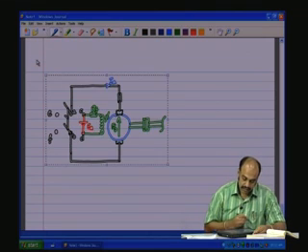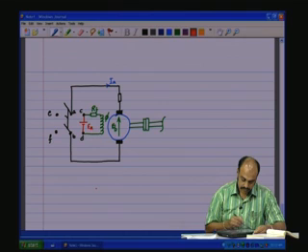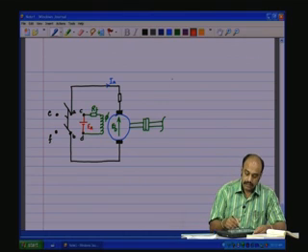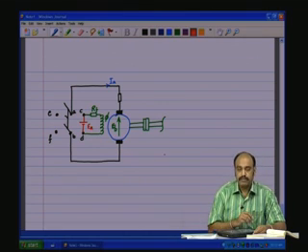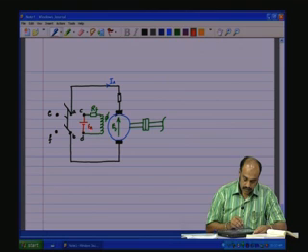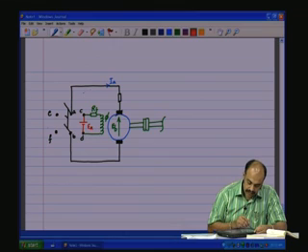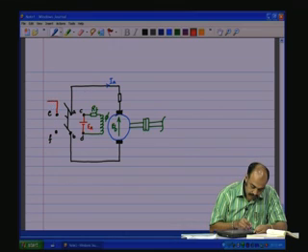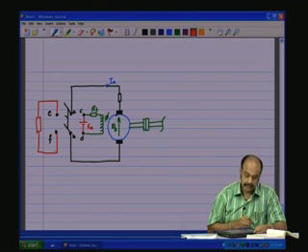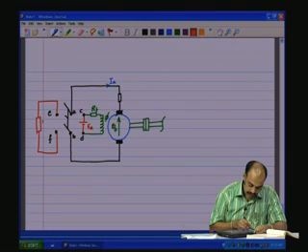So, in dynamic braking, what we do is, the energy stored in the inertia of the mechanical domain is going to get reflected as EB. It is a generator. Now, that EB, we will try to remove it by connecting a resistor here, let us say RB.